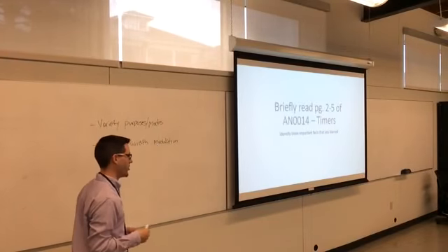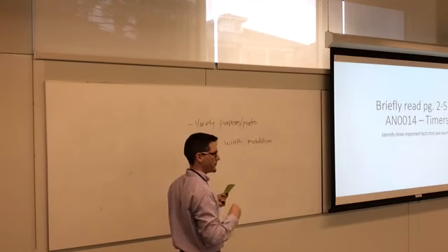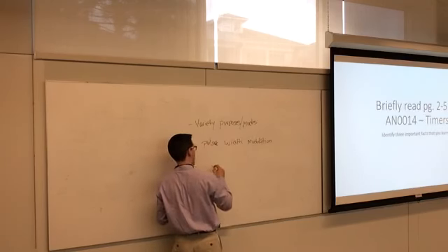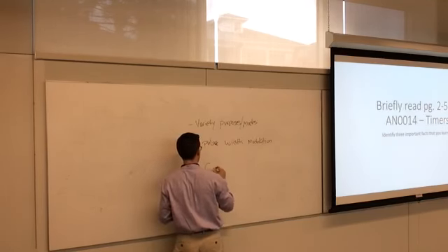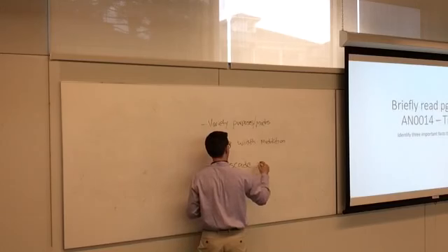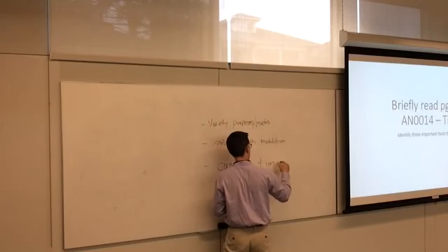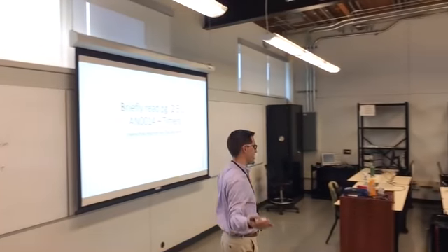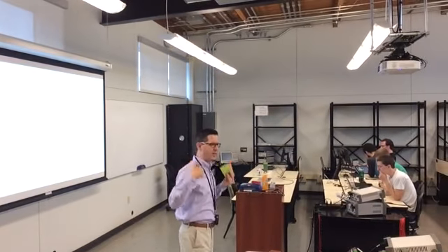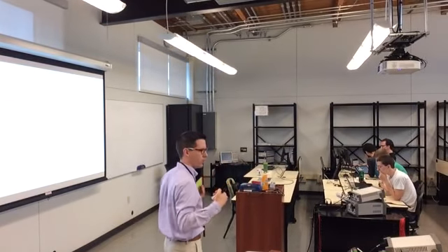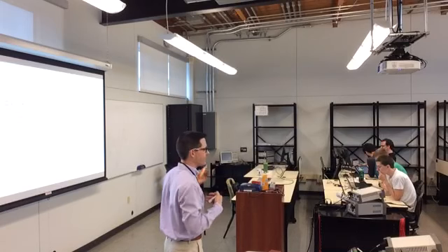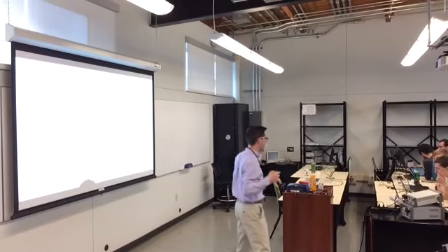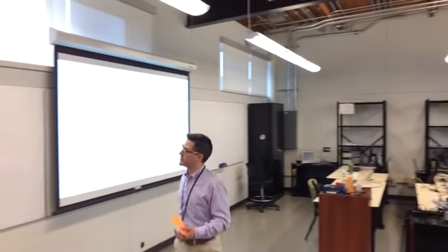Darren, what's something you found out? So more bits if you have 3 timers. Okay, so how big is each timer? 16 bits. Okay, so each timer is 16 bits wide. That means it can hold a 16-bit number. If you need to time more things, if you need to store a larger value, you can cascade the timers to get more bits. You can string them all together. It's 16 times 3.